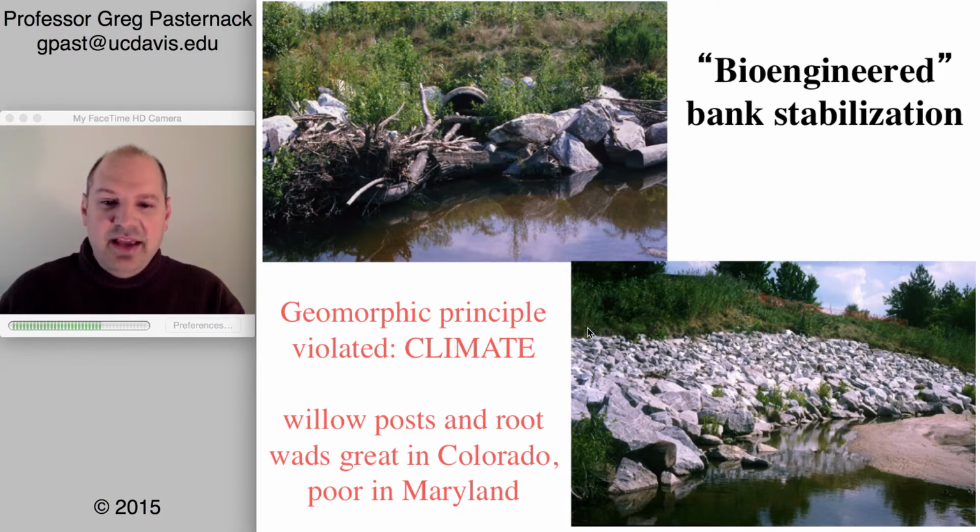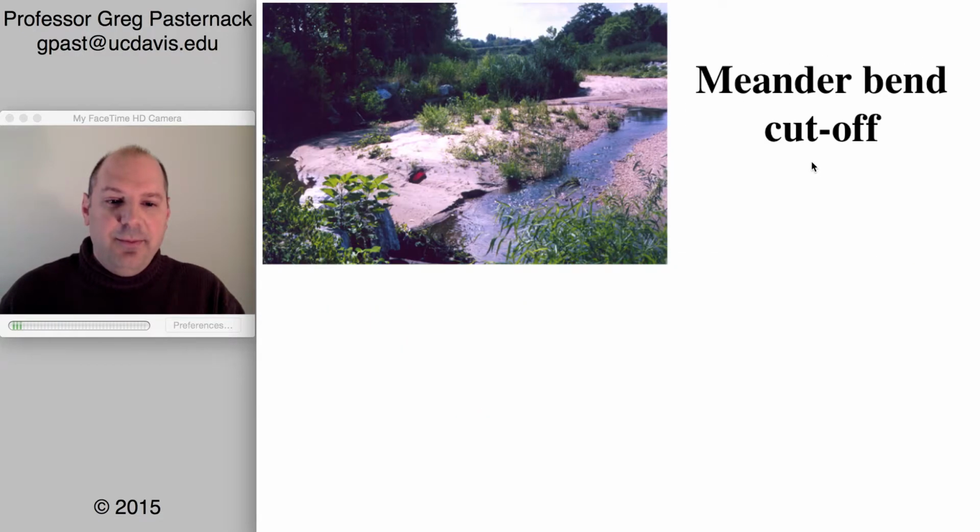And this is a violation of climatic principles in general because this willow post is something that works well in a little bit more arid climate like Colorado, where you may actually have a few years to get that stabilization, but it just fails in a state like Maryland with a temperate climate with high flows every year. It's just not going to hold up.